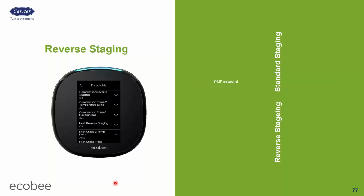So let's say I have a 74-degree cooling set point. That means I'm going to turn the cooling stage 1 on when it's 74.5 because I left it at the half a degree differential that we previously talked about. And then the default differential for stage 2 is typically 2 degrees. So that means I'm going to turn on stage 2 when I get up to 76 degrees. So my set point is 74. Stage 1 turns on at 74.5. If it continues to get warmer in there at 76, I'm going to bang on another stage. All right? That's pretty normal sequencing.